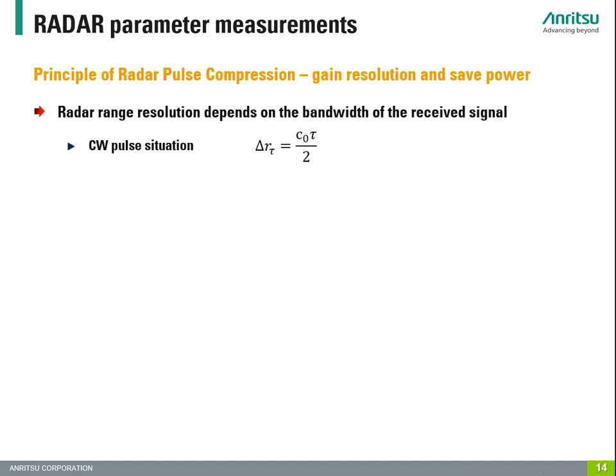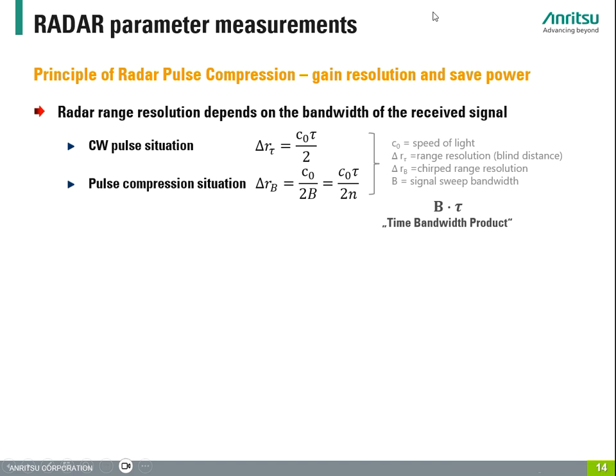The range resolution is usually purely dependent on the pulse width, also called tau, of a radar pulse. Applying a time-dependent modulation onto the pulse while the pulse is transmitted allows, on the receiver's side, by the use of so-called matched filters, to differentiate between targets that are within the pulse length. The compression ratio, also called time bandwidth product, enables a much higher target distinguishability.